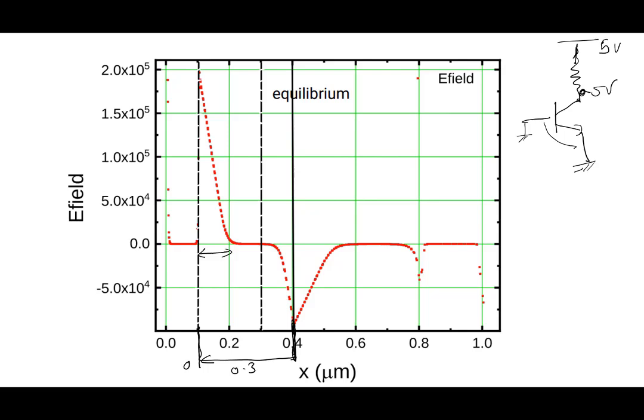So this junction width is maximum, because the base emitter junction is normally forward bias or zero bias. While when you apply 5 volt here, compared to equilibrium, this will further move left. Now what may happen is, under this situation, if the two depletion regions touch, then we say this is punch through. These things happen in MOSFETs also. Here we are talking about depletion regions due to collector and emitter touching each other. There we talk about drain and source maybe touching each other, influencing each other, or coming too close to each other. So that's the problem.